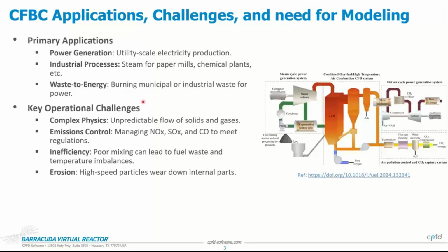With that said, with any type of industrial equipment, there are always some operational as well as design challenges, right? The first thing obviously is just the physics involved in the system. So you're talking about the hydrodynamics of the gas and the solids interacting with each other. On top of it, you also have reactions which are taking place, both in the gas phase as well as in the solid phase itself. Once, let's say, you do operate the reactor well, you have to deal with the problem of emissions control. You want to minimize your pollutant formation, and if you do form pollutants, you want to make sure that you're trying to capture them before they leave the reactor.